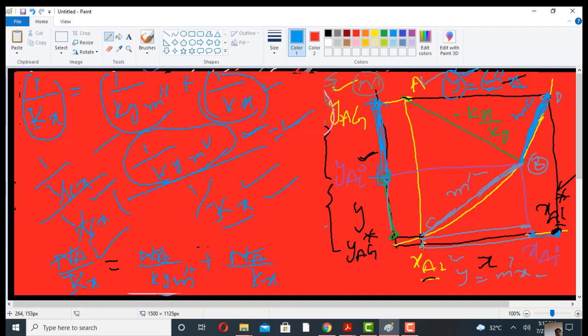So these resistances are very important in the absorption of gases in the liquid. Some gases are very soluble in the liquid, some gases are strongly soluble, some gases are insoluble in the liquid. If a gas is very soluble in the liquid, it means that the only resistance will be provided by the gas phase to the component transport.